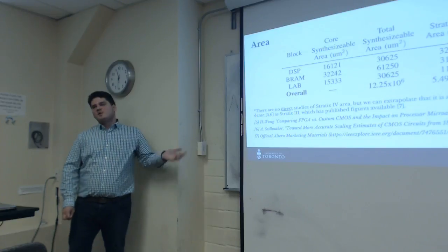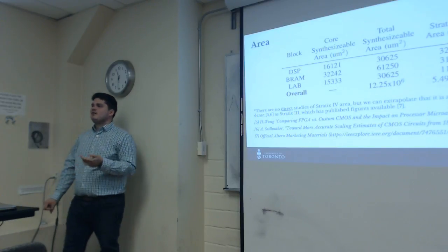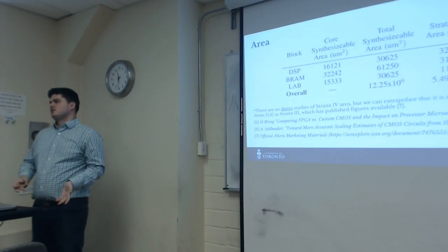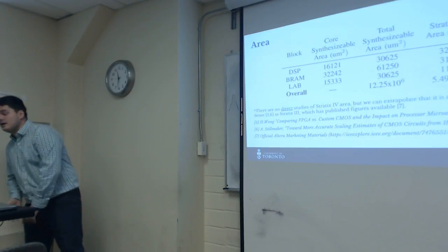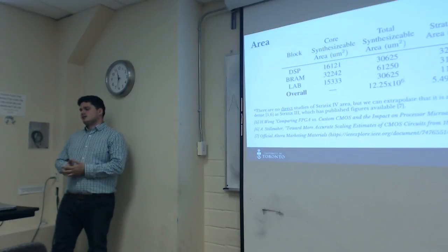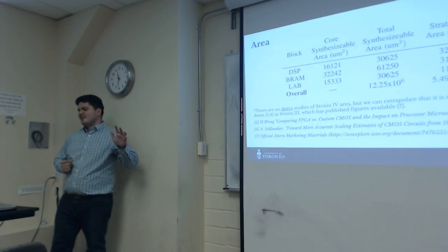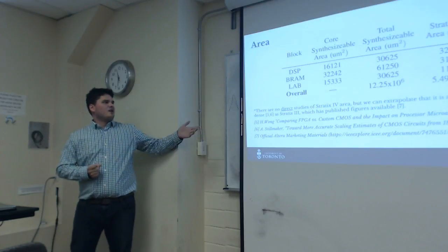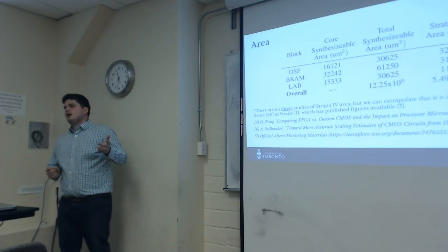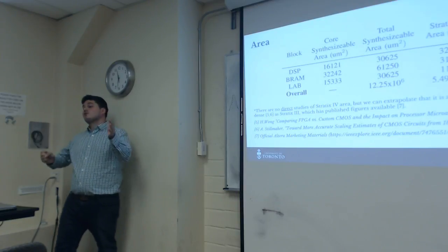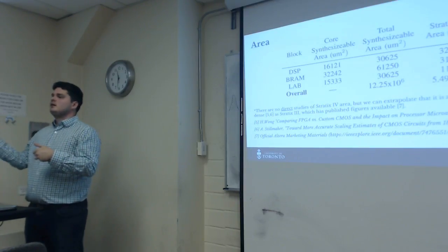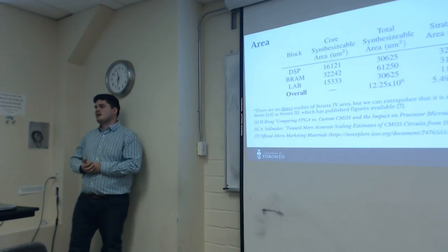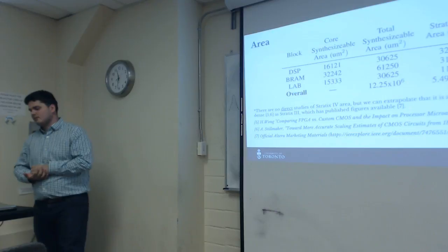So we do know that we can make it smaller. Having looked at the ratio between full custom multiplexers and standard cell multiplexers and the density we're aiming at, I know we can get this smaller. I guess I am inferring that from other information, but it's definitely true that the routing is costing us on every single block. No matter what block you add, the routing is still going to take up a lot of area. So it's a common element. It's half the area. We need to make it smaller to get better performance.